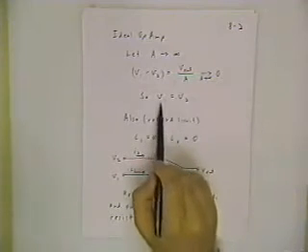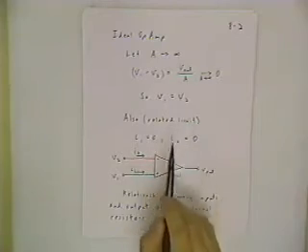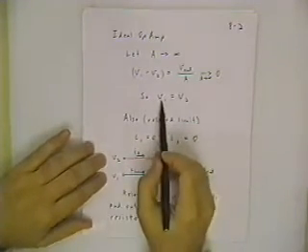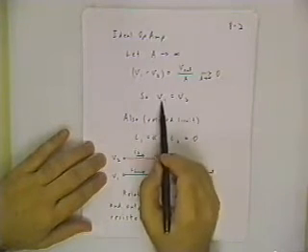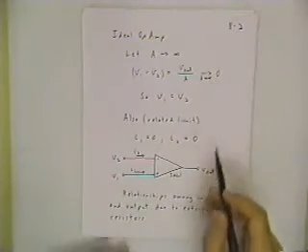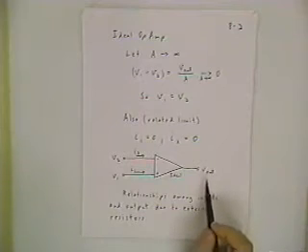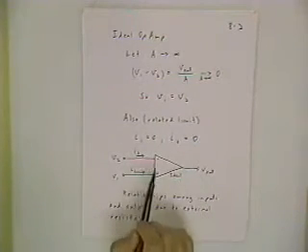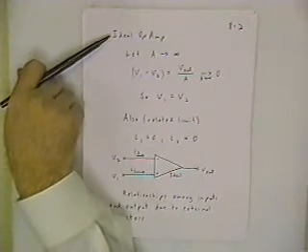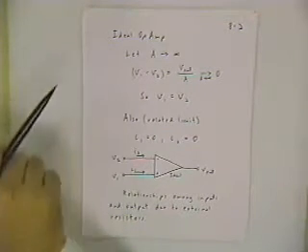So this peculiar looking situation occurs. In the ideal op-amp, the two input voltages are identical, and that difference V1 minus V2 equals 0, that 0 effectively is multiplied by an infinity to give you a finite answer. So it seems fairly bizarre when I say it that way. The way to rationalize it is to remember this ideal op-amp is really just a useful approximation. It's a real close approximation to the way a real op-amp works.